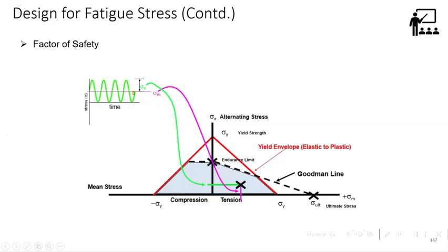So for this combination, you know the stress amplitude and mean stress, it falls here. And if you have that curve, alternate stress versus mean stress, with tension on the x-axis and compression, obviously this red line is very generic, because in structures we don't allow yielding, so the mean stress also should not go to yielding, and your endurance amplitude should not go beyond yielding.